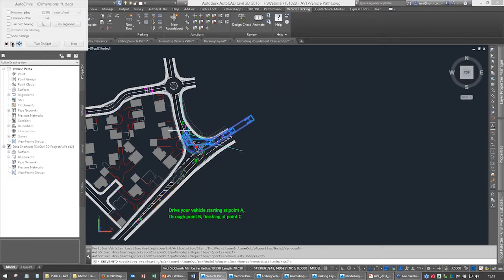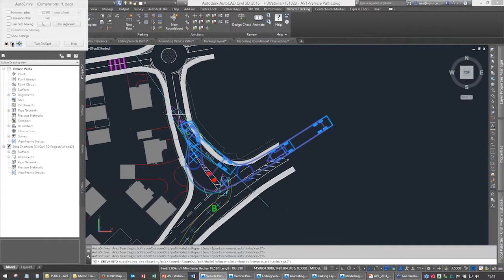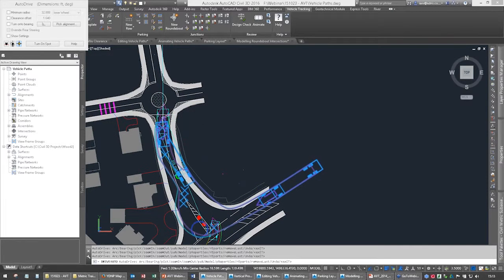Obviously it's going to struggle to get around this corner. You get used to driving these things, just spending a bit of time, because you can see with an articulated lorry, the problem with a lot of these things is oversteering. And you get used to driving them as you get around, because in the program world, if you were playing a game, you can pretty much go from full left lock to full right lock really quickly using your little game controller. But in the real world, you have to turn this big, massive, heavy steering wheel, and this will simulate that. So we have a turning lock timing as well. So if we're on full right-hand lock, you're not going to be able to immediately straighten that up.